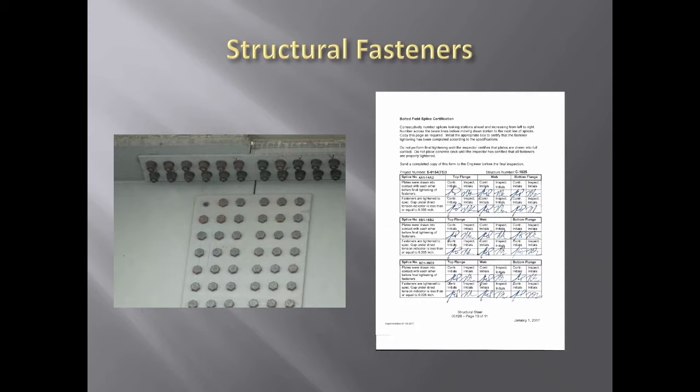During the process, after we've gone through the bolting procedure and set up with the guys, normally what we do when they start setting girders, we'll stay in with the bolting crews and actually go up while they're installing the bolts and watch them install them, tighten them up and get them to the right tension. Make sure that going forward right off the bat that all the guys know how tight we want them so that we don't have to go back and tighten up bolts after the fact.